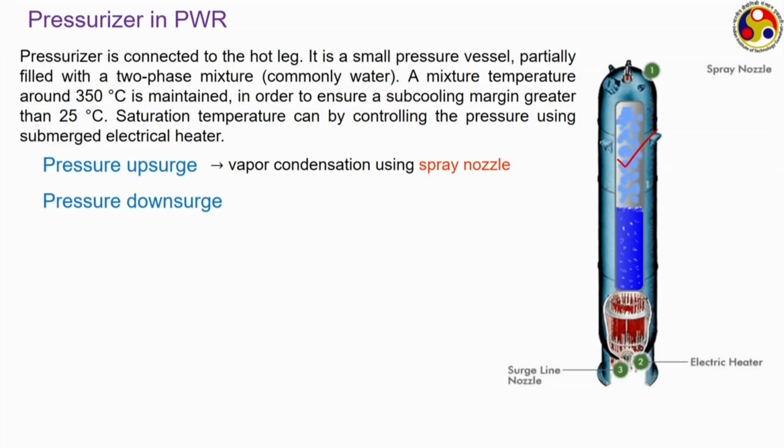So, this vapor will try to expand, but as the pressure has fallen, both liquid and vapor part remain at the saturation temperature corresponding to the initial higher pressure. So, some liquid from this free surface will try to evaporate and occupy that portion, thereby gaining equality or equilibrium in terms of pressure. I think I told something wrong, I would like to correct this once more.